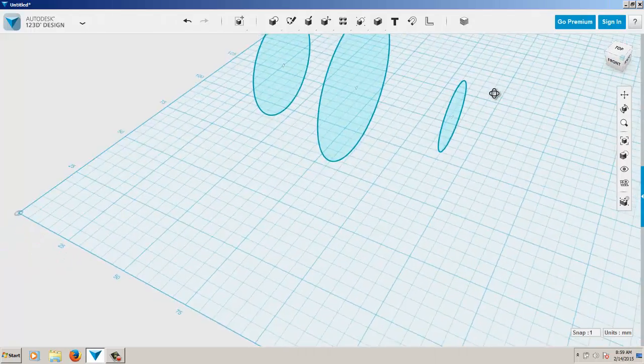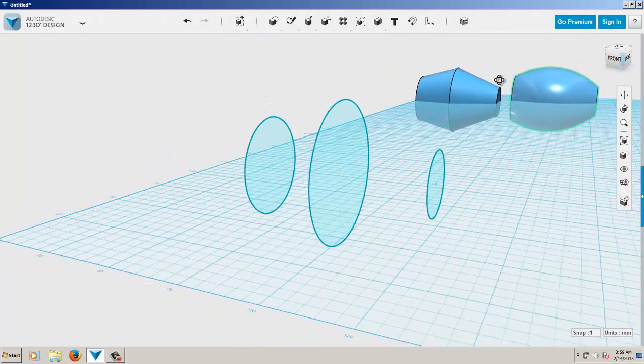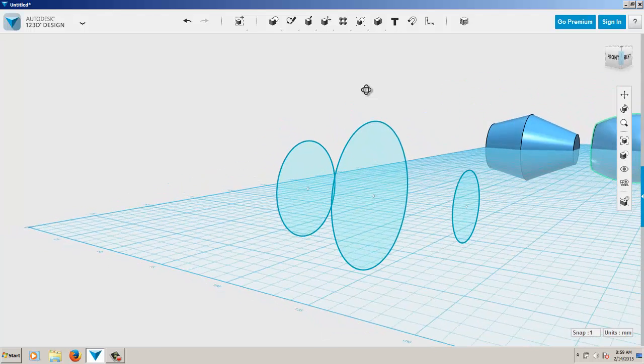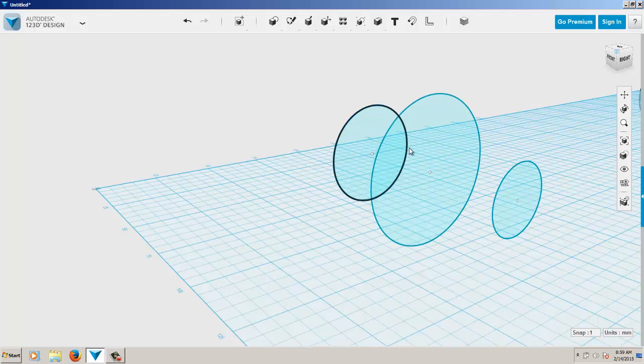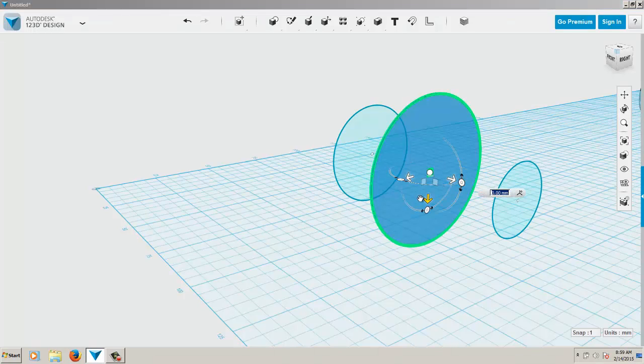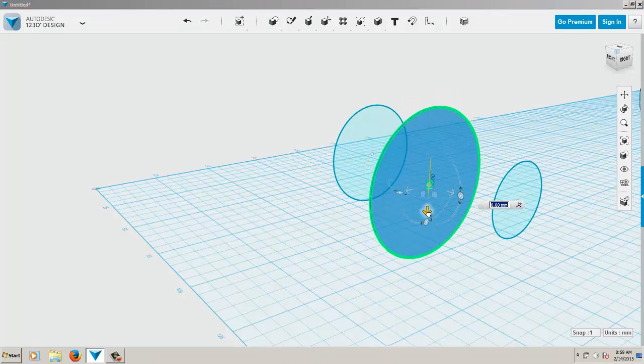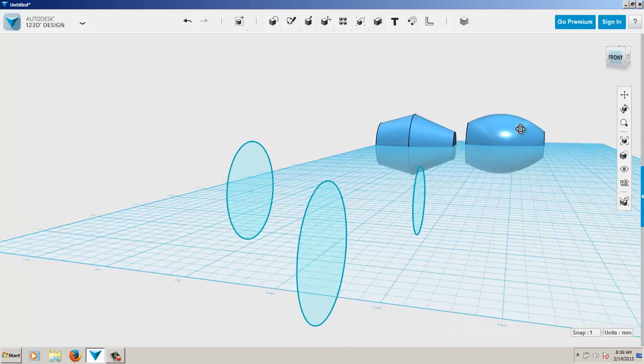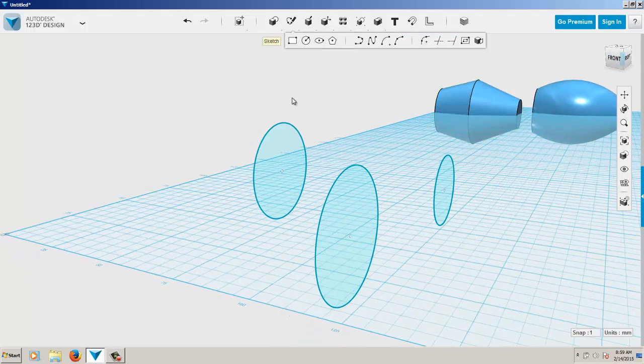So that's one basic way of lofting. To give you some ideas as to what else can be done with this, we'll just keep these circles in place, and then I'm going to select the second one, and I'm going to use my moving tool, and maybe slide this one down a ways and go back, and then I'm going to do this with the smoothing aspect.